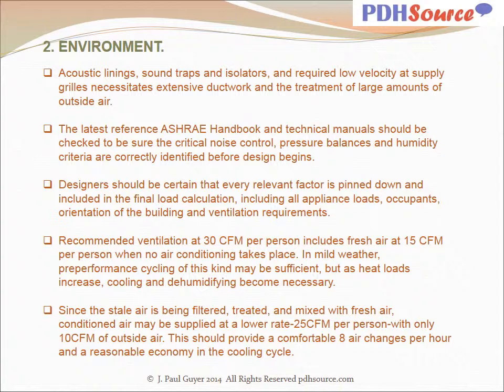Designers should be certain that every relevant factor is pinned down and included in the final load calculation, including all appliance loads, occupants, orientation of the building, and ventilation requirements.